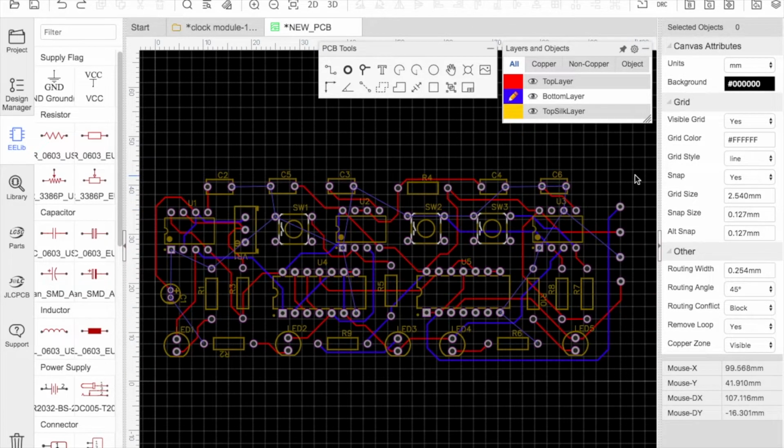Okay, so now we've got pads where we can plug in power and ground, and we have an output and an inverted output. Now I want to add some holes into the PCB so that I can fit M5 screws in to bolt it down to a wooden board or something like that. So I'll put them in 4 corners.